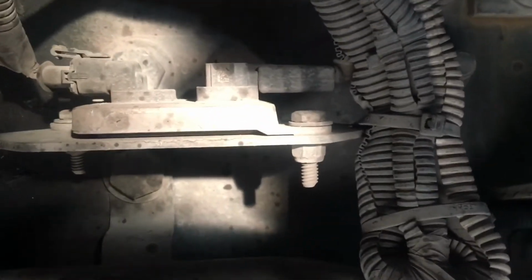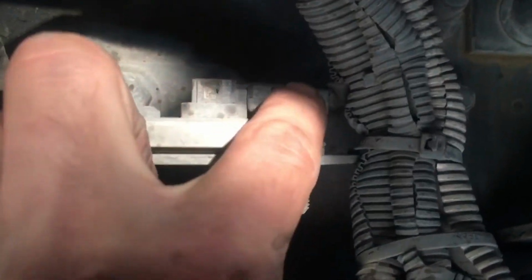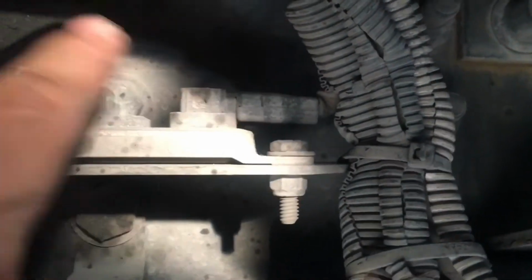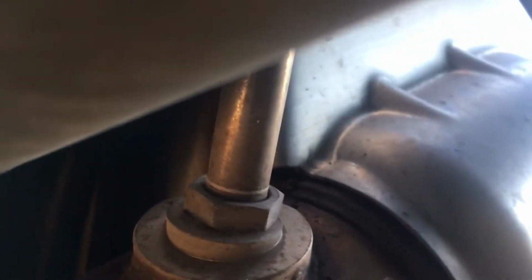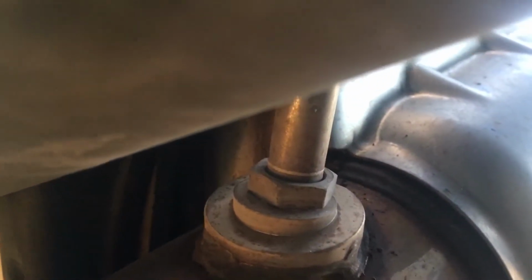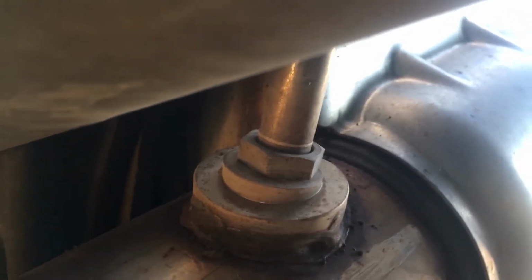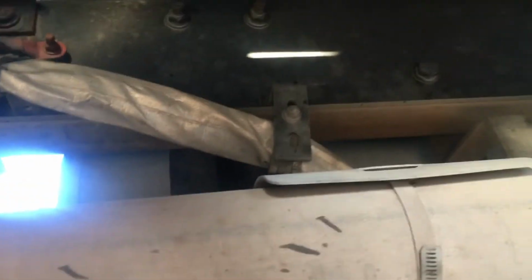And again, it's another module that has the plug which goes to your ECM, and then this plug is not removable, not serviceable. That goes to your outlet NOx sensor. Remove the 2 bolts, unplug it in order to replace that one. But this one, like I said, was replaced before. So your outlet NOx sensor is always after the SCR, and the exhaust pipe runs straight out the back of the truck. So it's picking up how much NOx you're putting out into the environment.